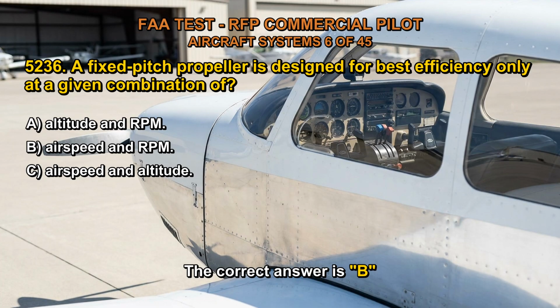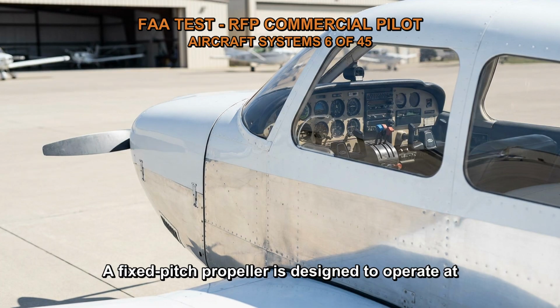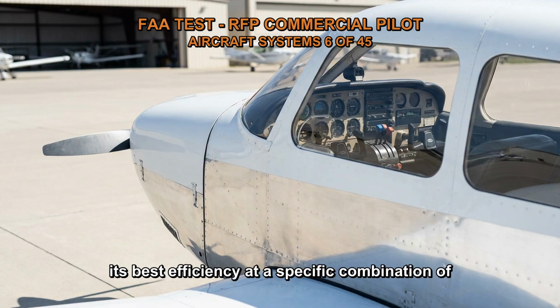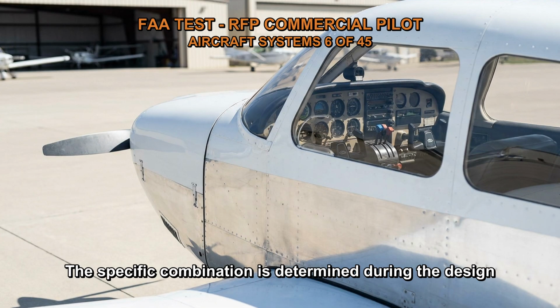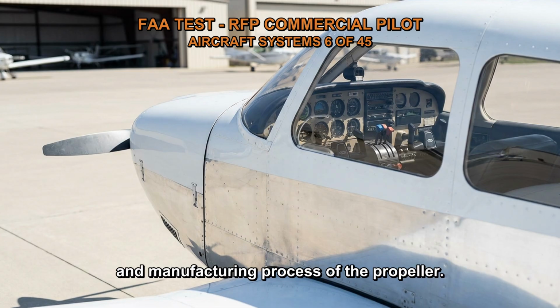The correct answer is B. A fixed-pitch propeller is designed to operate at its best efficiency at a specific combination of airspeed and RPM, engine revolutions per minute. The specific combination is determined during the design and manufacturing process of the propeller.